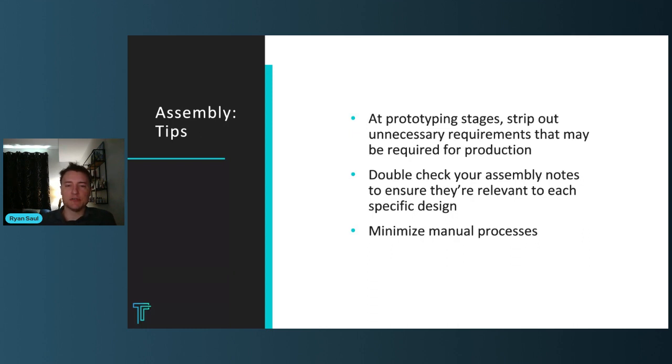It's not just for the cleanliness of the design. You're adding a significant amount of cost at the end of your design. It's so easy from a unit cost perspective to move the copper on your fab relative to soldering additional wires on your board post-assembly. So definitely, I would minimize that if you possibly can.